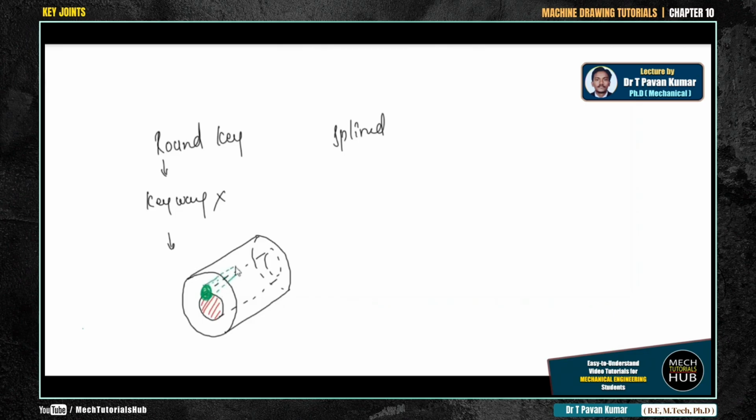Now this particular round key will also have a taper section. It is not linear like a cylinder; it is somewhat like a cone. So there will be a taper section. Material will be drilled and taken out. Then a round key is fabricated, of a different, stronger material than the hub and the shaft, something of this kind. Now this will be knocked inside.